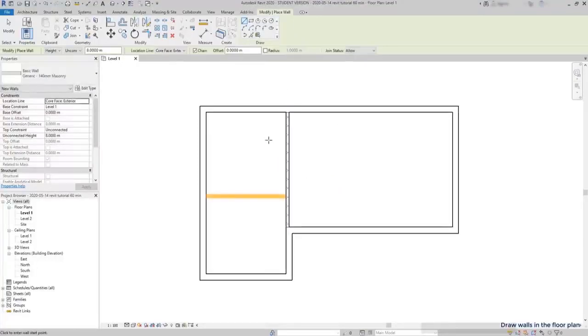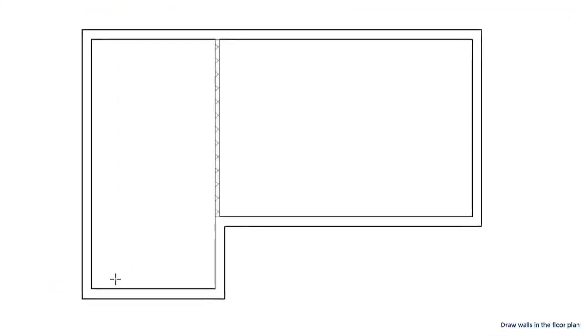Then, the wall that divides the left part in 2 rooms is located at this distance of 3.8 from that external wall. One good way to make it is going to the endpoint at the corner, drag up and type the distance.